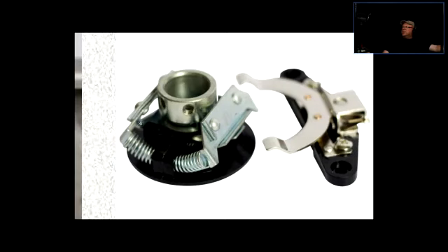As soon as this whole element starts spinning, there is going to be centrifugal force applied to that. Those weights are going to be pushed towards the outside of this disk, and they're going to become heavy enough that they're going to open.